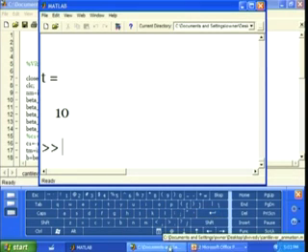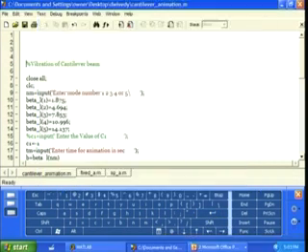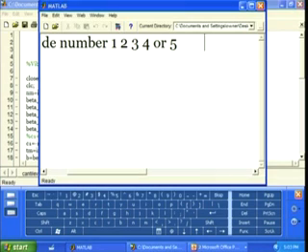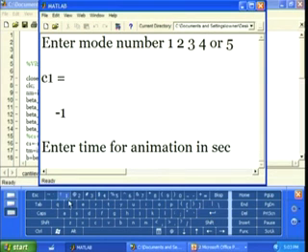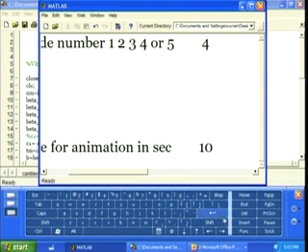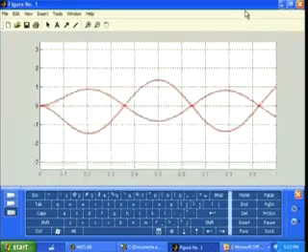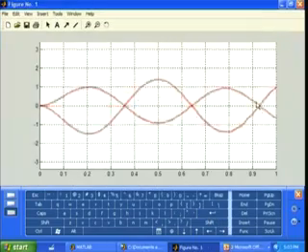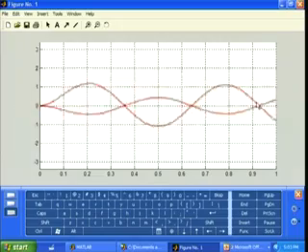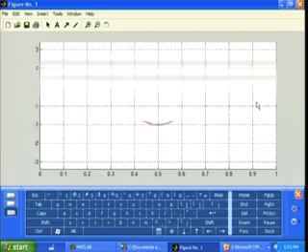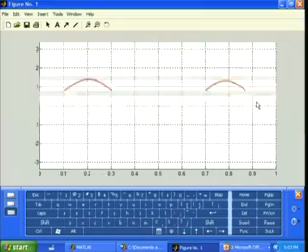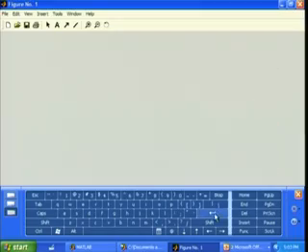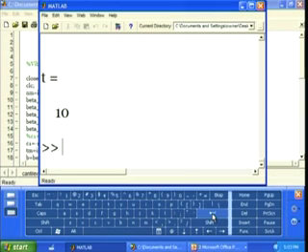To see the fourth mode, clearly you can observe 3 nodes are formed in the cantilever beam. Similarly, for higher modes n minus 1 nodes you can find, and the free end will vibrate with a maximum, and at the fixed end there is 0 deflection and the slope is 0 also.